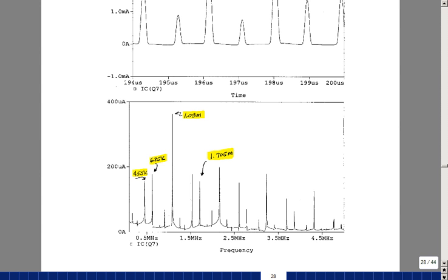There's a feedback path that once the oscillator gets started, it maintains itself and eventually shuts off the transistor and then turns it back on again. So a very non-linear oscillation. And again, you wouldn't see this by just looking at the voltages in the circuit. They appear to be all sinusoidal, but the currents that are going on in this transistor circuit are pulse waveforms, but they have these specific frequencies.